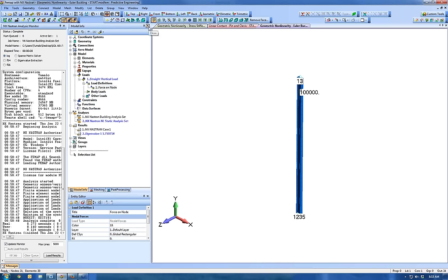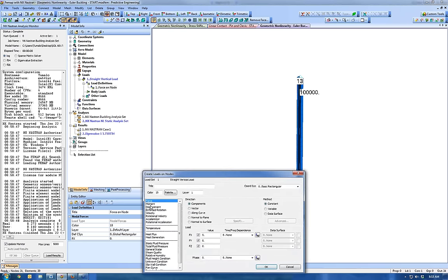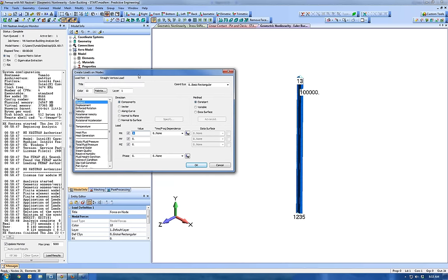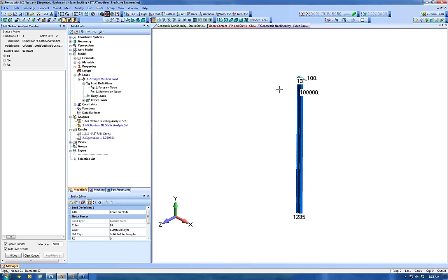The other thing I need to do here is instigate the buckling. In our buckling white paper, we discuss a variety of methods, whether you add some imperfections to the model or apply some loads to help this happen. I'm going to use a little bit of bending moment right here, about the x direction, and I'm going to start with 100 inch-pounds. Now let's run the nonlinear analysis.